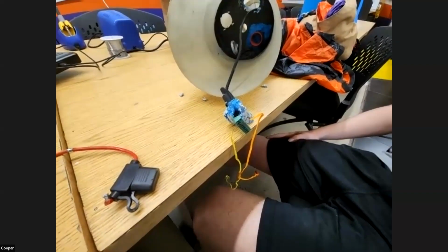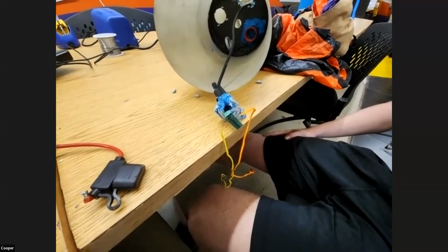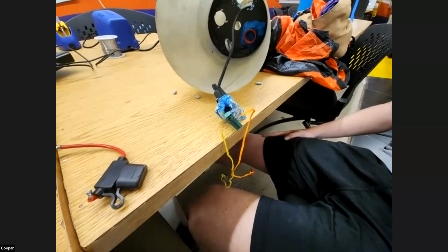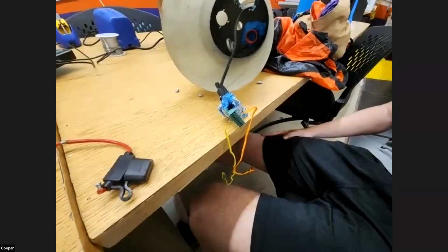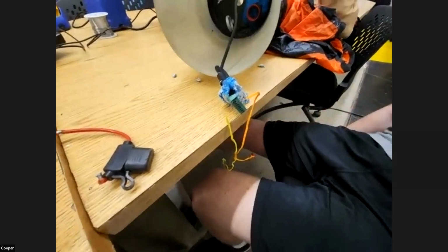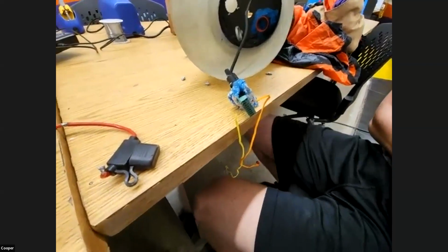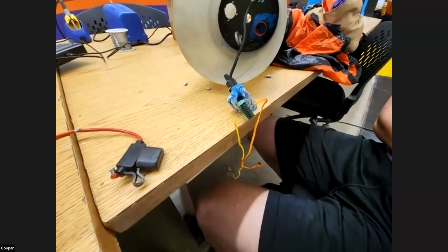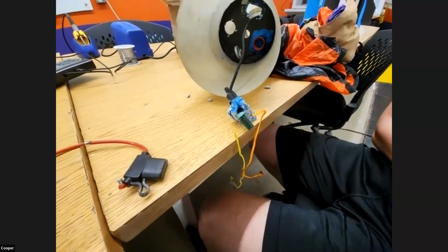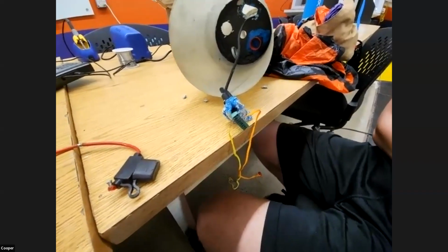And the moment the physical connection point is gone, it should be straight into the insulation. That helps you avoid two wires accidentally crossing over. Trying to get tape in between each one of those little notches is going to be a nightmare. It's going to be a mass of tape. So I love those things to a certain point, but I also dislike them greatly because of that challenge.